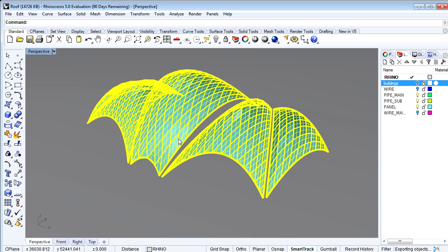Please note that now we have converted a highly complex Rhino model into a set of GDL objects that are part of a single file container called an LCF file. It's important to establish an easy-to-follow workflow that will retain separate logical parts within the exported Rhino roof structure, and that will also enable us to monitor and easily update the imported model in ARCHICAD. This LCF export option is also advised to enable ARCHICAD's performance optimization algorithm to work seamlessly on an imported large and complex Rhino model.